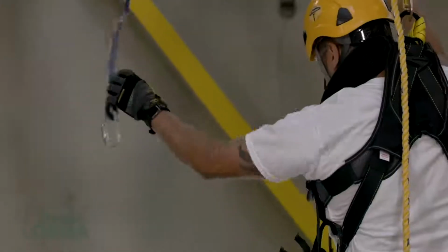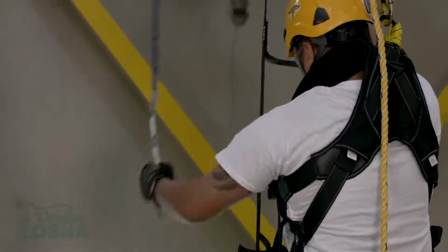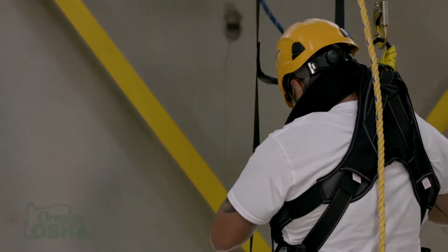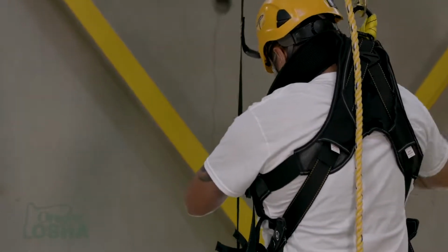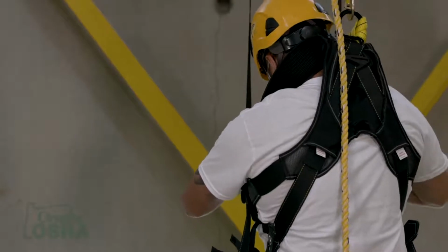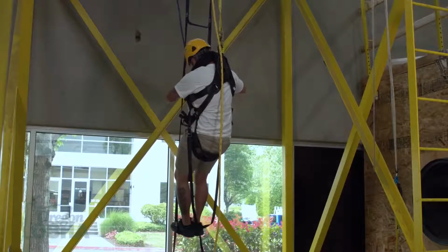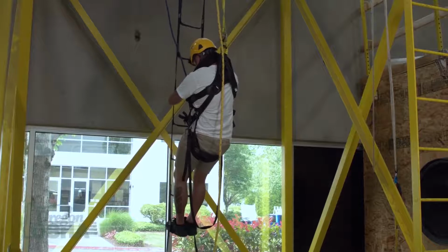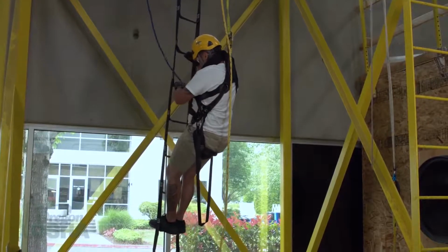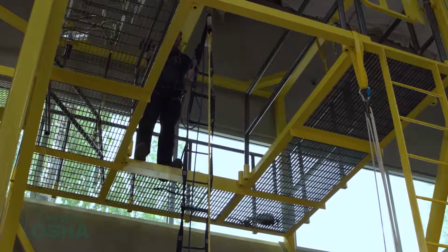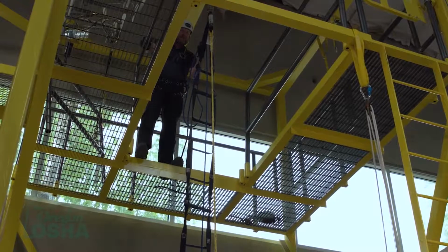Hey Dan, can you reach that? Can you get that sucker attached? Wait, it'll come back to you. All right, go ahead and attach that to your D-ring, man. And the idea here is that as he tries to climb up, whether he's coming all the way up or we're just climbing him up enough to get him disconnected from his anchorage, we don't want him to have another fall, because climbing a ladder can be a challenging thing after you've just been a fall victim.